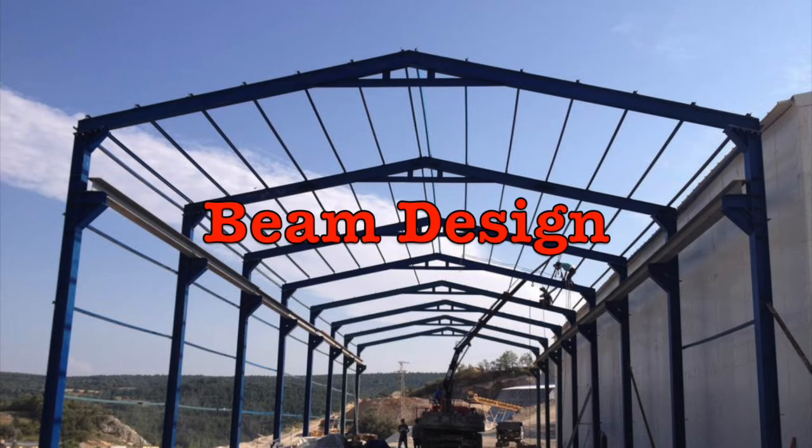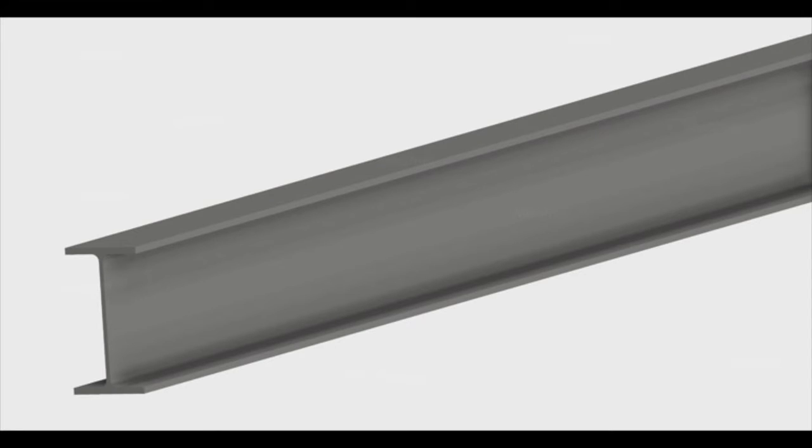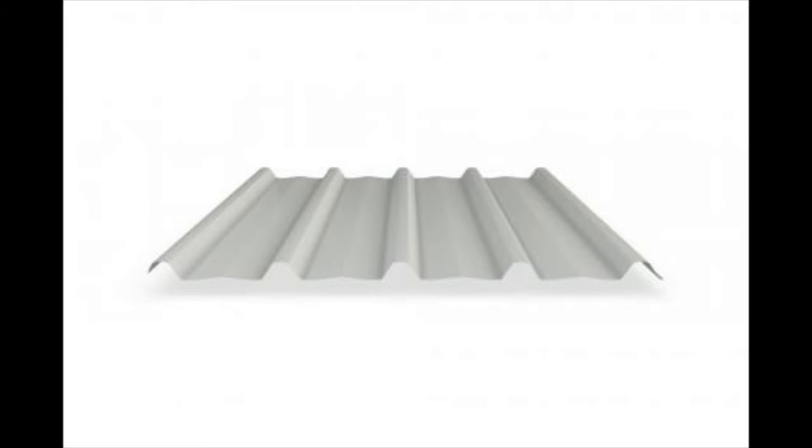For the first part of the assignment, we were to design the dead and live loads on Beam 1 and Beam 2. Our beams were to be universal beams as per the One Steel catalogue. Beam 1 was a rafter, this meaning that it had to support the dead load weight of the sheeting, purlins, ceiling, insulation and services. The roof sheeting we were to use was Colorbond trim deck. Its weight was 4.93 kilos per metre squared.